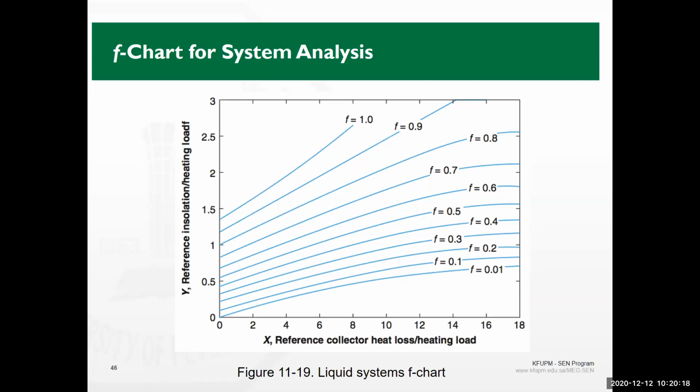But if you are talking about a water heating system utilizing boilers run by diesel, diesel is cheap. In this case, you can find that using solar collectors to reach an F equal to 0.7 or 0.8 may have a payback period of about 20 years or so.